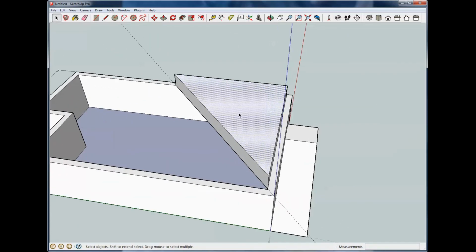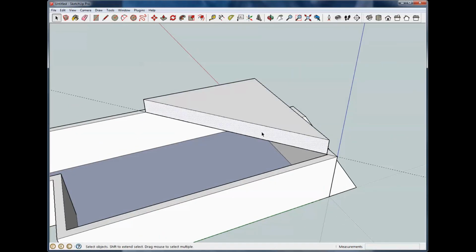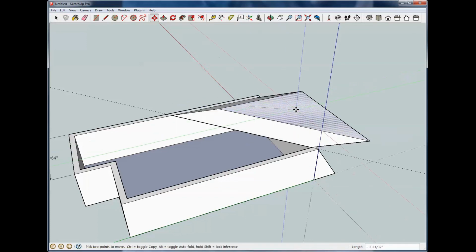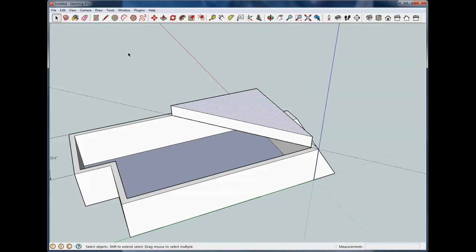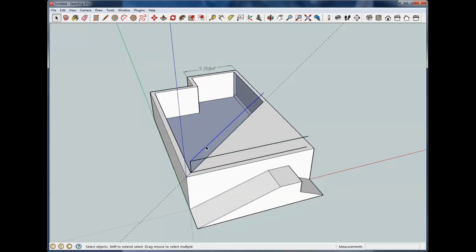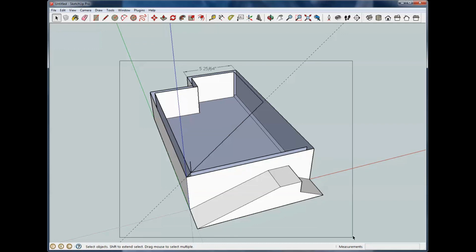And notice we didn't make it a group, so to get rid of it, we can edit all those entities separately. Notice we try to click on it to delete and see how it's pulling around, because we don't have a group. So let's delete that. See, we've got to do all the separate deals. Causes all kinds of chaos. I got the top of my box there. That wasn't a group either. So make sure you group your stuff.